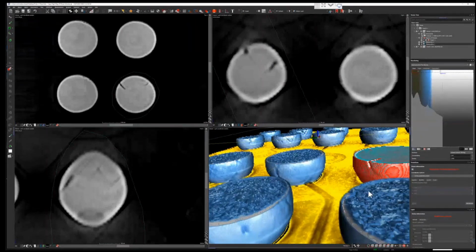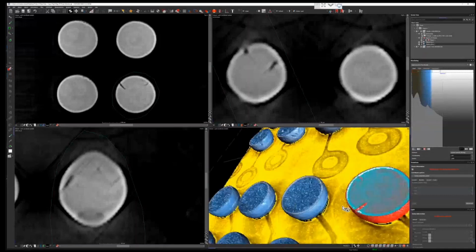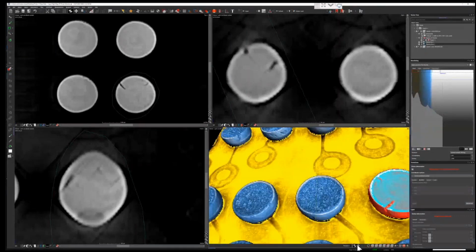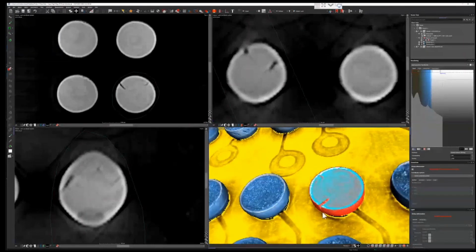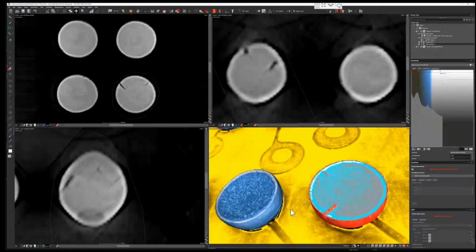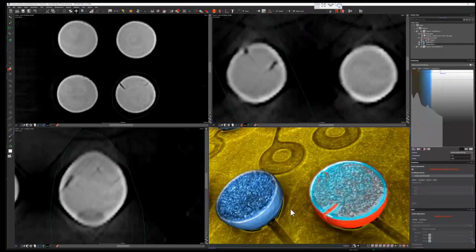Trying to bring you in closer here. Oh, there we go. I'll zoom in, and you can see exactly where the crack propagates from to the point of where about it isn't. Is it going right the way across the ball or just partly through the ball? In this case, just partly through.